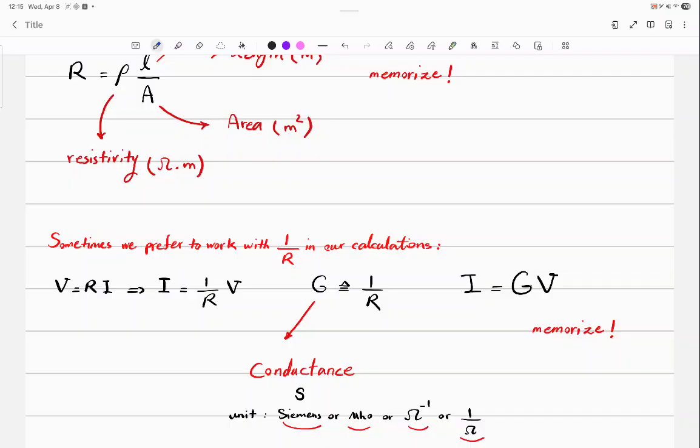The algebraic sum of all the currents entering a node, or in parentheses exiting a node, stick to one of them, is equal to 0. And what does that mean? What if it is not 0? What is the nature of current? Current is electrons. Charge, right? Charge moving. So if KCL doesn't hold, it's violating some fundamental rule: conservation of charge.